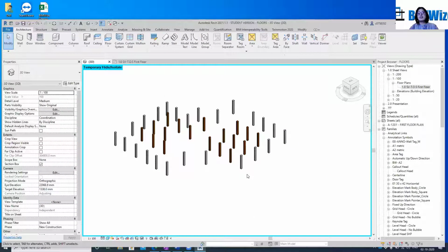So this is a very unique feature that I really like in Revit, is that I can isolate elements, I can work on elements, or I can isolate the category. So let's say if I was just working on, and this also helps me create amazing floor plans. You know, if I'm showing like a floor to floor relation, if let's say I want to just isolate all the floors and see how circulation in my floors is going.